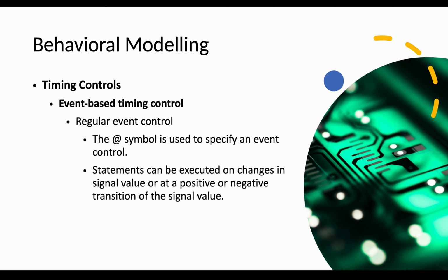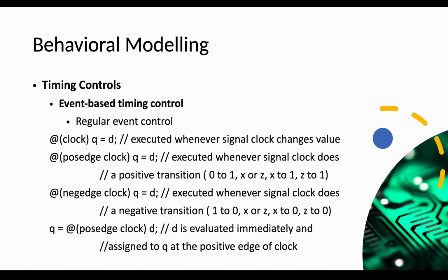Regular event control. The @ symbol is used to specify an event control. Statements can be executed on changes in signal value or at a positive or negative transition of a signal value. Here is an example of how we give this regular event control.